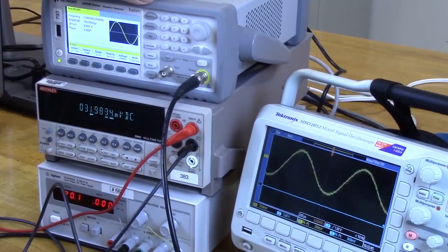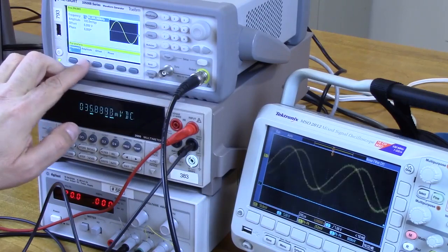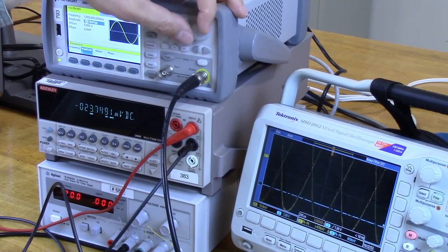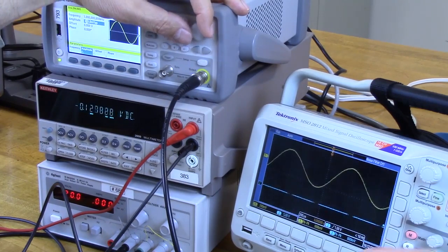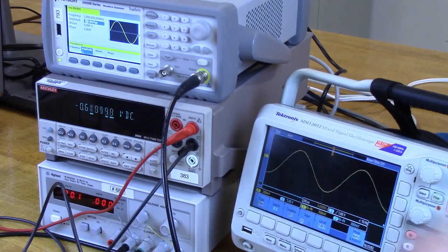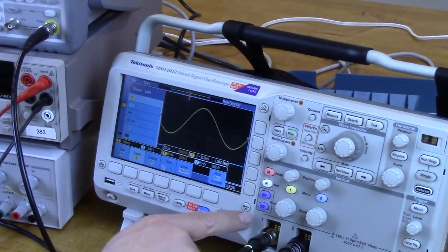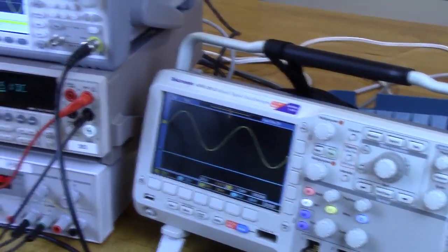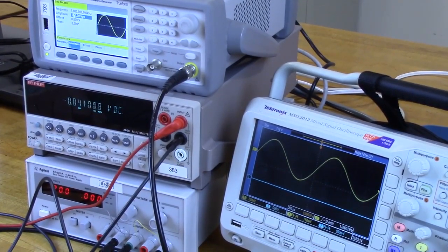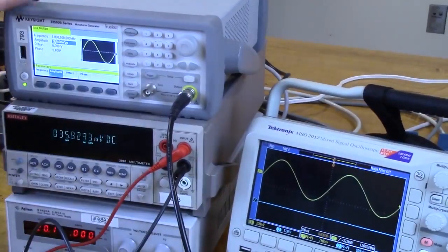Let's make it bigger than that. So let's go to amplitude, parameters, amplitude, and let's just turn it up, make it a little bit bigger. Looks a little better. Now, if we want that to hold still, we can use the triggering menu to tell it to look at channel 1. And it'll actually hold still and not give us a headache. So on this channel 1, we have a nice sine wave. It's about 1 kilohertz, and it's about half a volt peak to peak. Okay, so this is all set.